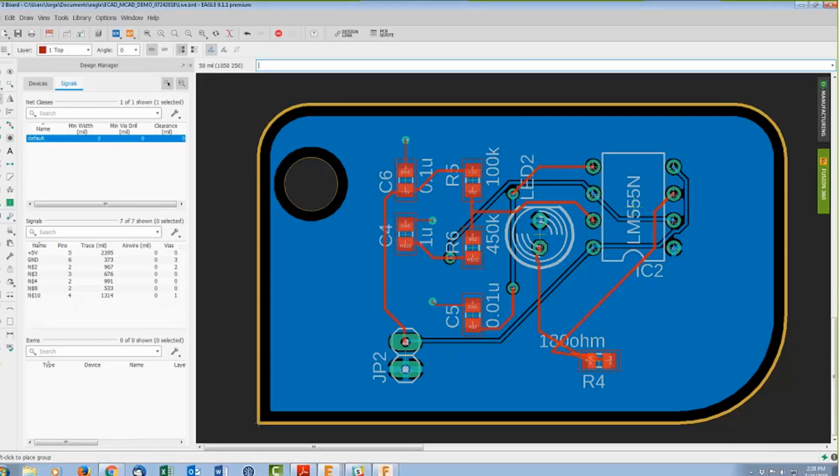You know? So you could also do a route and go around, use a loop removal feature. Let's see if it'll catch it. Let's try that. Okay. Yeah, see? So you can do that. Now the width is obviously short, so I'll go ahead and change that. You can just type in width in the command line. So 10 mils is the right width. There we go. Perfect. And I'll fix this one because this is in a 45-degree angle, as you guys can see.